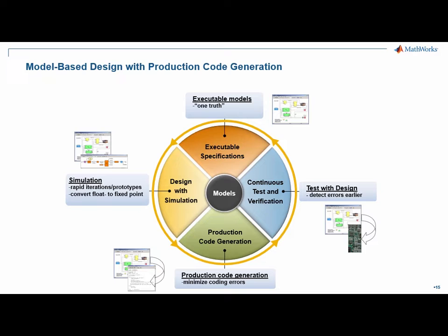You can execute the model as an executable specification by simulation. You can design using simulation, for example, convert floating point data to fixed point. You can generate code at any point in the process for prototyping or, as we will discuss, as part of the code that goes into your mass production device.